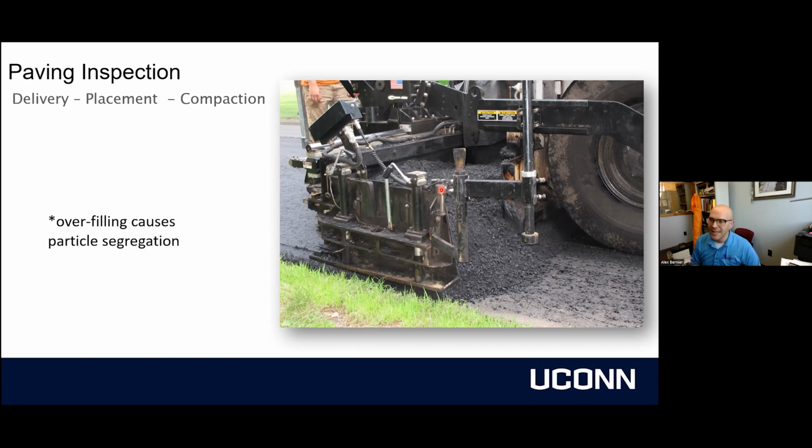Now, the reason this is a problem, if there's too much or too little material here, the auger is going to cause segregation. And if you remember, that's when the large particles and the small particles move differently, just like your cornflakes or your bag of potato chips, right? You can think of segregation, and this happens with rocks as it would with potato chips. The large particles stay on the top, the smaller particles will trickle down, right? When you get to the end of your bag of chips, what's left? It's only the small stuff.